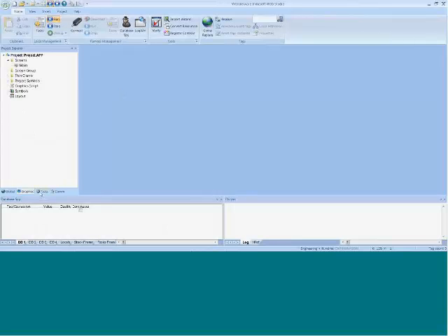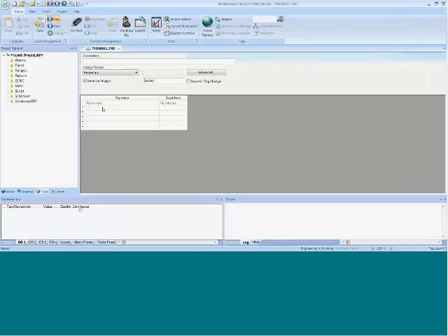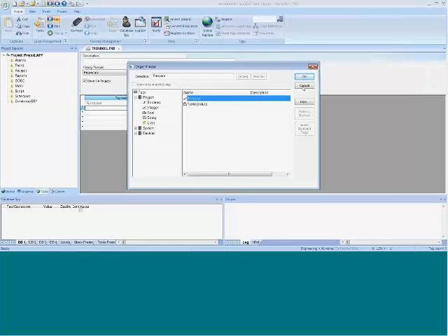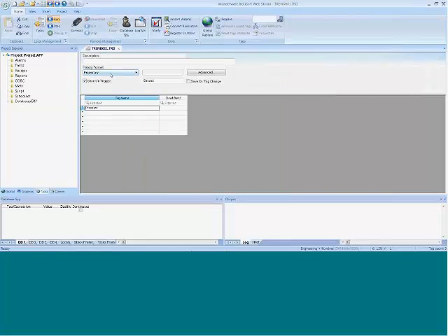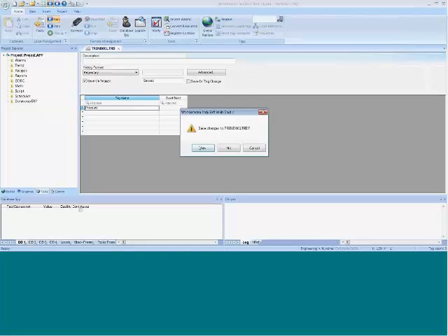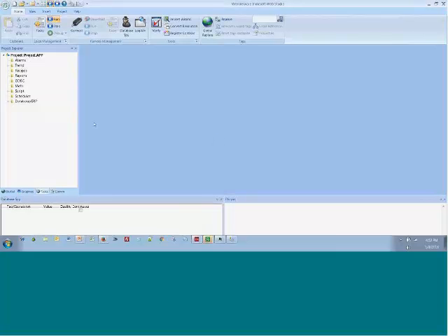And now what I'm going to do is, down here in the Tasks tab, create a trend or a logging worksheet where I might put that pressure in here. And instead of going to a file on the hard drive, which is the default, I'm going to add this connection to the database. Well, before I do that, I have to set up a connection to that database. So I'm going to go ahead and save this.